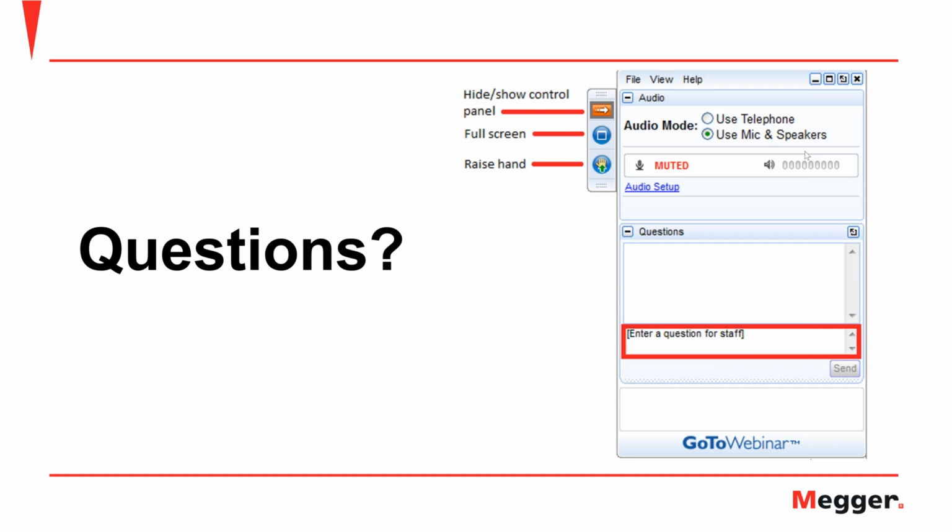That's for the possibility that what the utilities call an event occurs while the operator is doing the test. So the test itself is not dangerous, but if a fault current is going to ground while the operator is running the test, then yeah, the test setup can become part of that. So yes, use industry standard safety procedures, and just be careful.